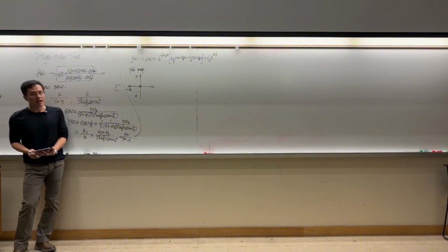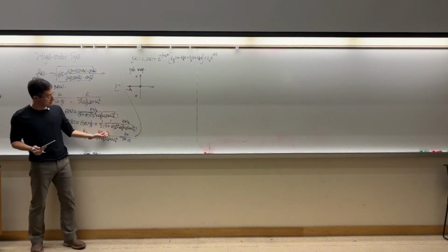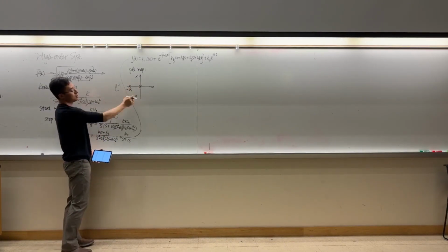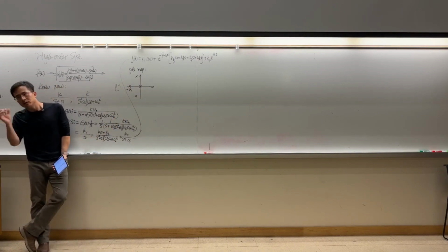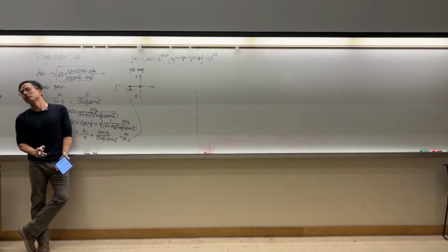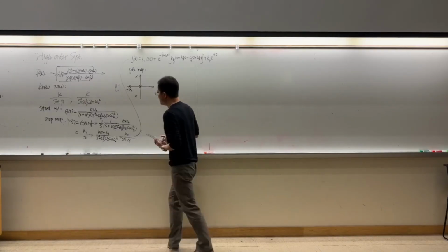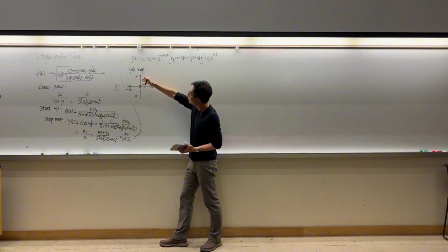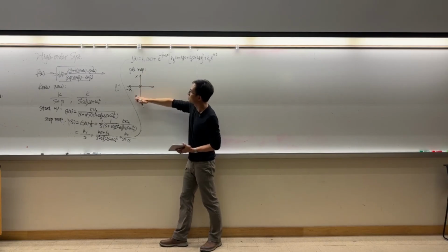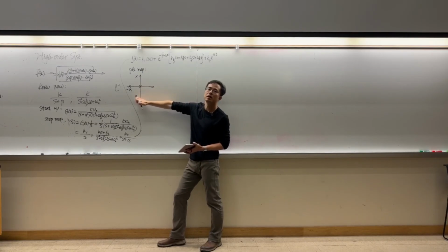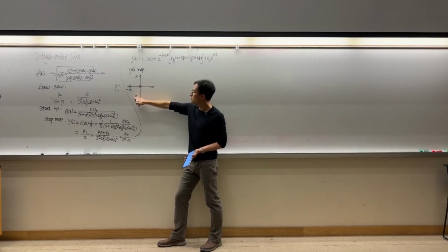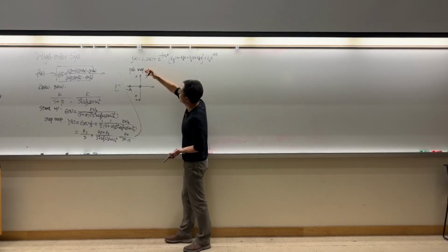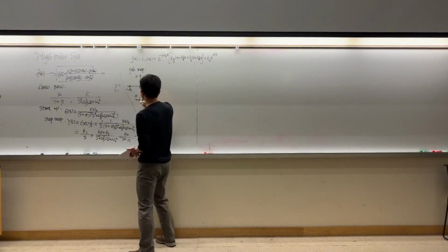So what I would like to do next is, suppose you're given a pole zero map like this, or more specifically, just a map of the poles. I would like to develop this intuition of how the response will look. Okay? So first of all, if this complex pole is closer to the imaginary axis, how would the response be? Would it be more oscillation or less oscillation? If this is moving in this direction, more oscillation, right? So it's closer to this marginal stability bound. So more oscillation this way.